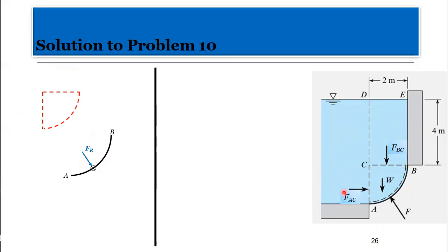So this fluid here will exert a pressure on this part of the wall, which is this, right? And then the top here, fluid will exert this on this part. So I'm talking about this part of the fluid, okay? So if we're able to talk about the weight here, we'll be able to use that to estimate what? The force FR, okay? Now, look at this here. The A here leaves an image A prime and B prime here. Remember C is here, right? Good. So meaning that the weight exerted or the resultant force acting on this gate is the same thing as the force acting on that.